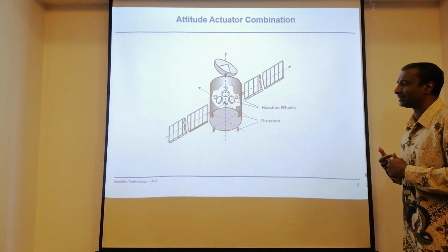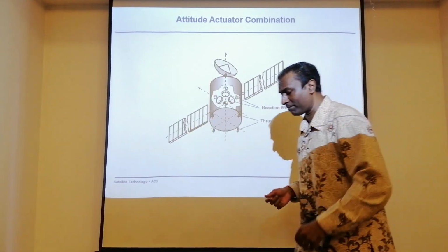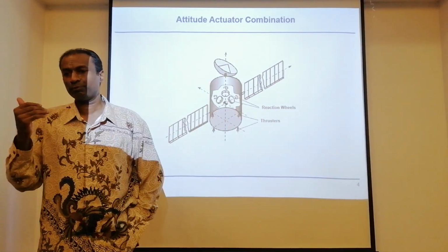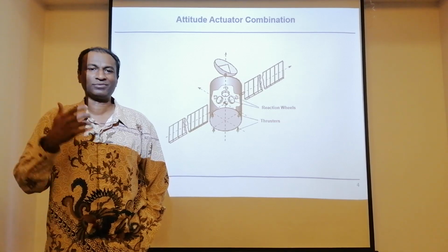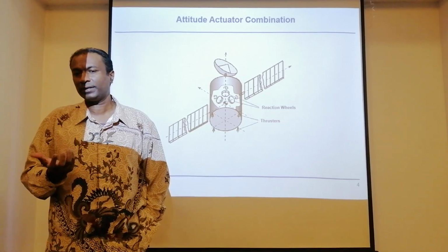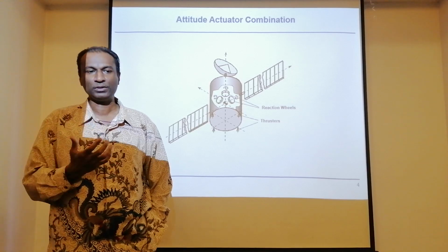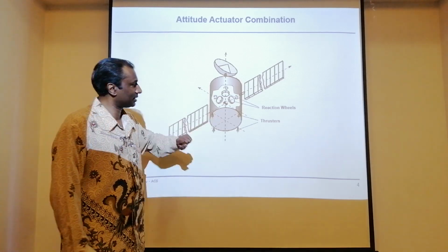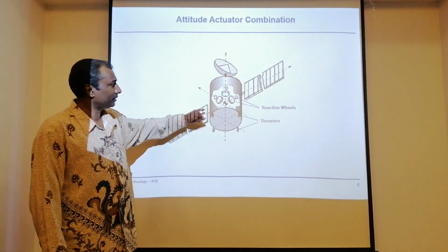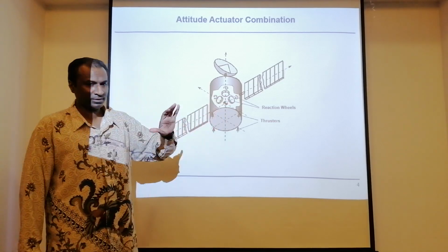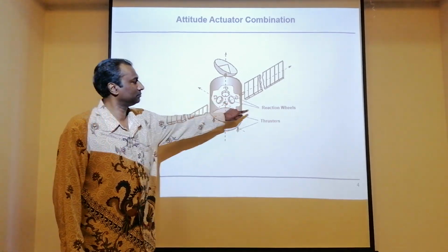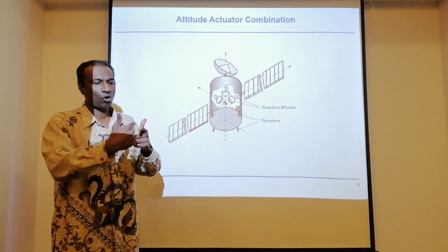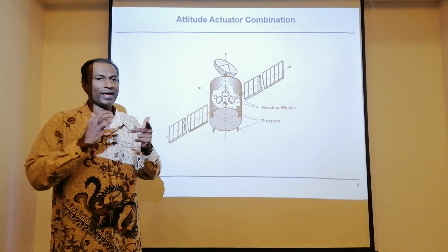Now, let me combine these two options that we had last time. We were exposed to propulsion systems. We call them thrusters in the satellite, and we also have momentum wheels or even reaction wheels for stabilization. I bring all this and I start installing it in the satellite. What I have here, I have 3 axes. I need to be stabilizing 3 axes. I can have 3 reaction wheels. Done. So I can induce a rotational motion in all those 3 axes, X, Y, and Z.